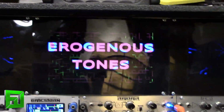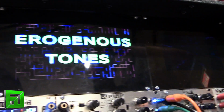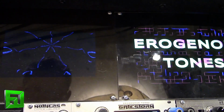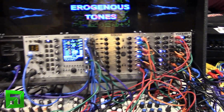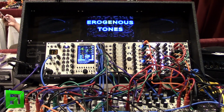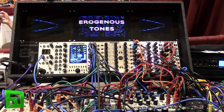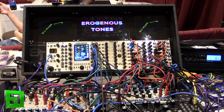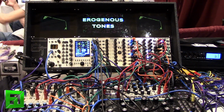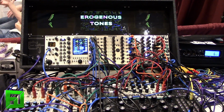What's going on with these visuals here? This stuff is crazy. Up top, we're prototyping some ideas of doing visuals with a Raspberry Pi. We've got 2 Raspberry Pis back there, and we wrote a bunch of custom code that's doing OpenGL ES shaders. I've got audio coming in through a USB audio interface, and I'm using that to generate textures and then modulate 3D geometry at the same time. That's awesome. We're thinking about turning this into an open source project, more or less, where it'll have 8 CV/gate in, pick whatever you want, a couple knobs, and a bunch of input and output video options, so people can use it with their VJ stuff.